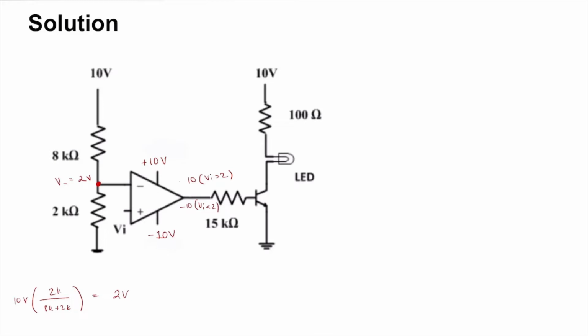So when the voltage here is plus 10, that is when plus VCC comes, you will now have current flowing into the base of the transistor, because now you have enough voltage to drop 0.7 across the base to emitter diode. This will cause the transistor to turn on and the LED will glow. It only has a drop of 1.5 volt.